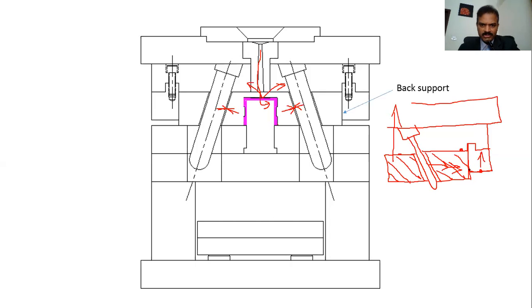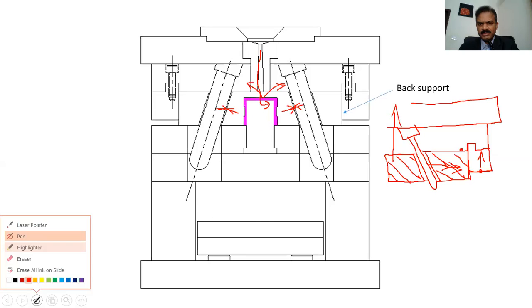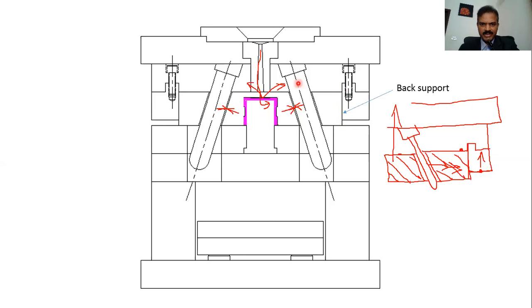So what is supposed to happen here? See here, something is in its way because it is a straight line. When the finger moves up, it is not going to allow the slide to move out because a solid muscular support block which is straight in line is still covering the back of it. So what is supposed to happen? The weakest point will break. Probably the finger is the weakest element here. So the finger will snap.